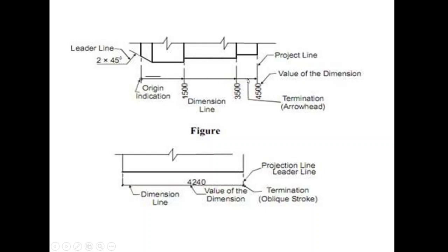Now keep in mind that the projection line and the dimension line should not intersect with each other. Here it is perpendicular, it is not intersecting.